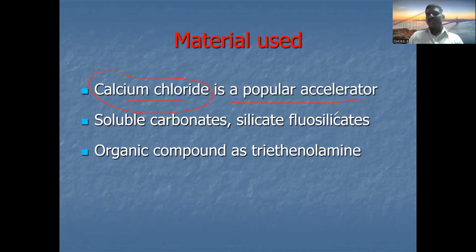Actually, admixtures are chemicals, and we use them for different purposes: early setting, or a retarder when we have to increase the setting time of the concrete.